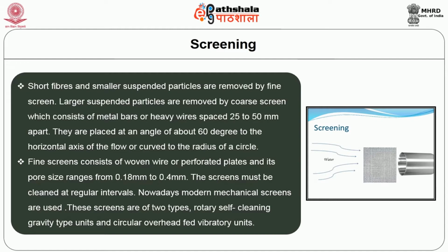The screens must be cleaned at regular intervals. Nowadays, modern mechanical screens are used. These screens are of 2 types: rotary, self-cleaning, gravity type units and circular, overhead-fed, vibratory units.